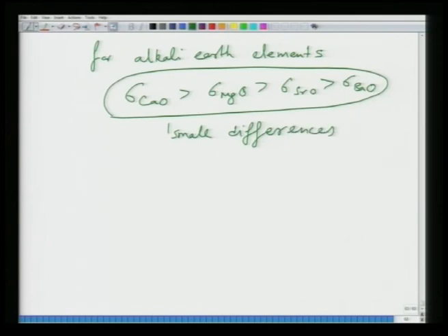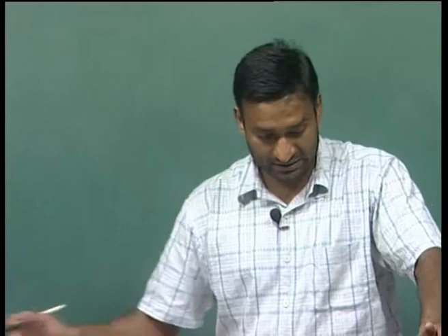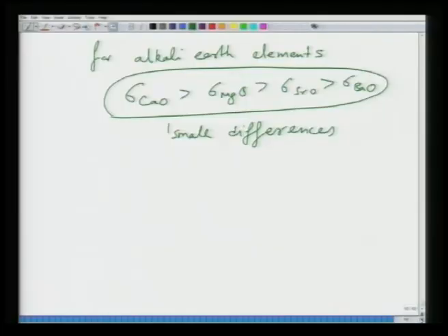So the effect on the increase of conductivity of silicate glasses is very large in case of alkali ions than in case of alkali earth ions, because alkali ions are much smaller and alkali earth ions are bigger, and once the ion becomes a bit too big, the effect on the conductivity is insignificant. Another category of conducting materials is conducting ionic solids, the fast ion conductors.